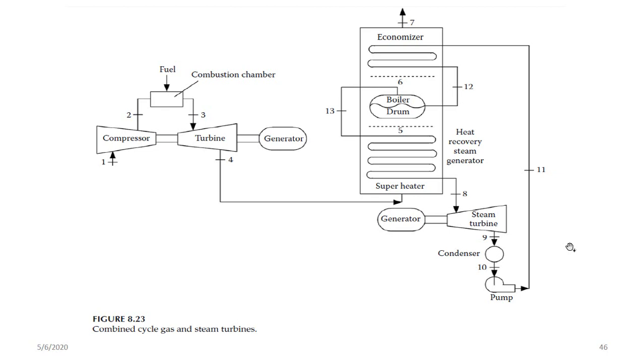of a certain dryness fraction, sufficient and convenient for power generation, because it's not every steam that is used for power generation. You need steam of a higher dryness fraction, closer to 1, because if steam is in form of droplets, then it can just erode the blades of the turbine. So you need steam which is superheated, meaning it will not condense, and that's what is used to generate electricity.